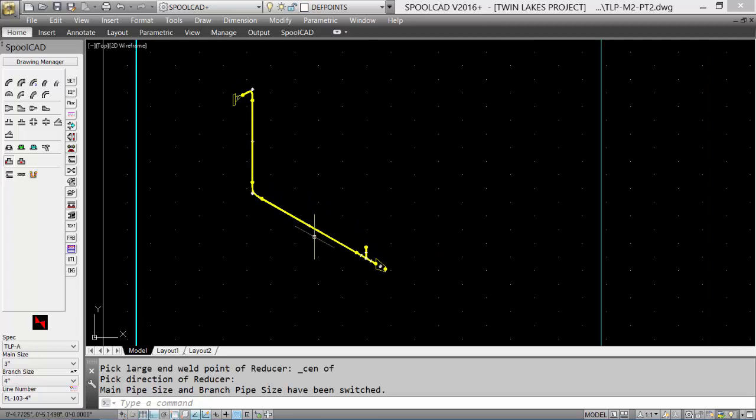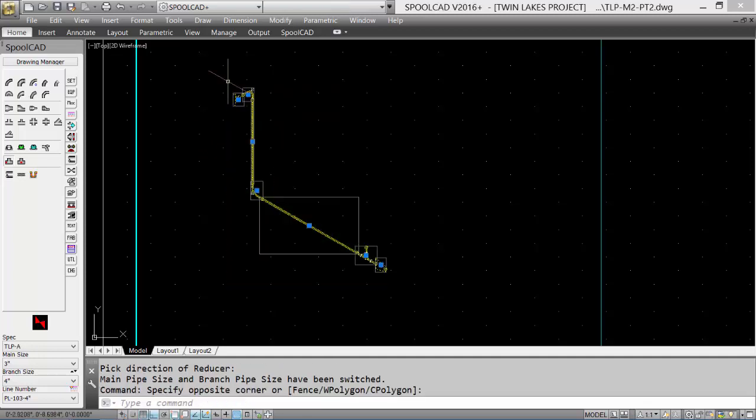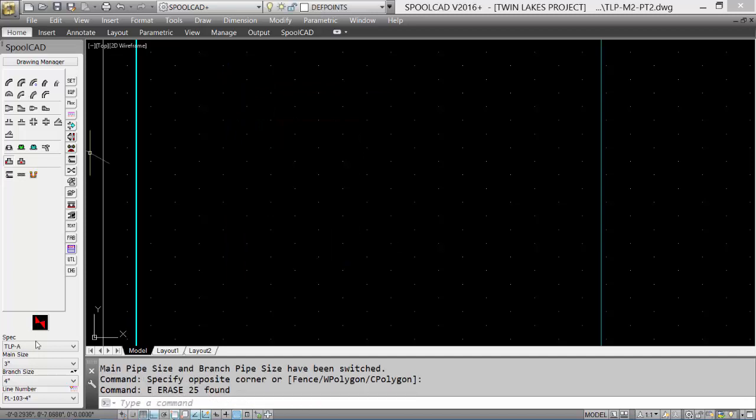Fairly straightforward, but you noticed I had to pick a lot of the start points using the AutoCAD object snaps. Endpoint, midpoint, center. What we can do now is turn on the autoroute feature to show you how it is automated. So let's repeat this pipe run. First we'll erase this one. We'll reset our values and our isoplane. Let's turn on the autoroute feature.